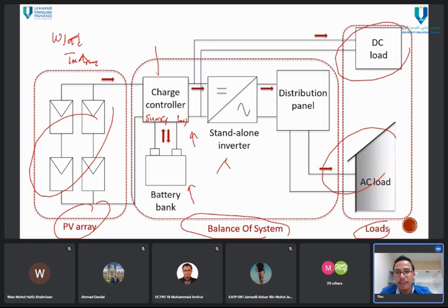We have learned before what the purpose of the charge controller is. The most important thing is that the charge controller is used when you have a battery connection, in order to prevent over-discharging and also overcharging of the battery. That's why we need the charge controller. Like we learned before, the MPPT charge controller is the most suggested one. Please forget the PWM and series controller, shunt and so on. Just focus on the MPPT charge controller.